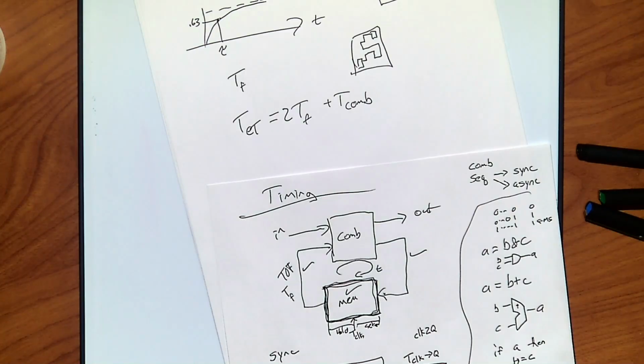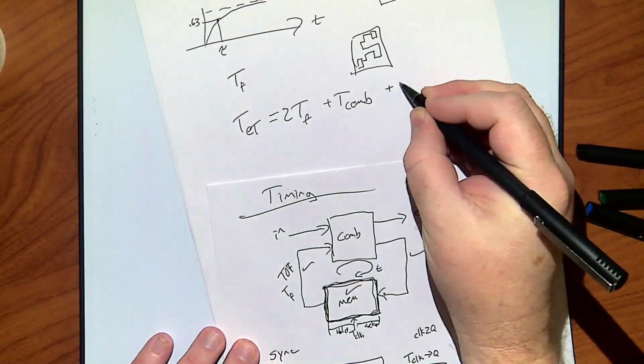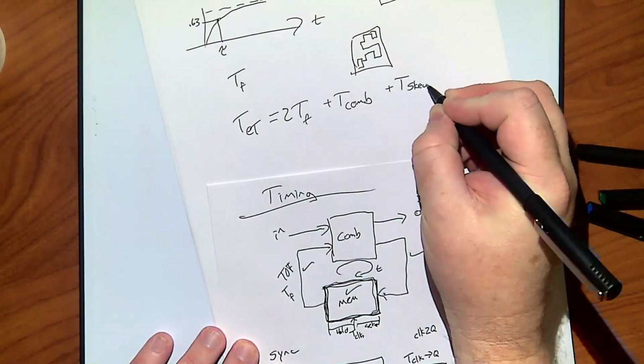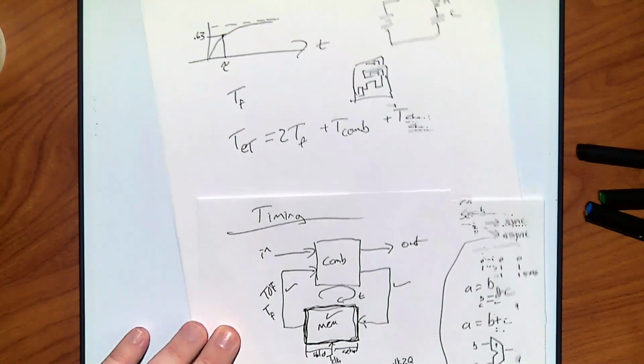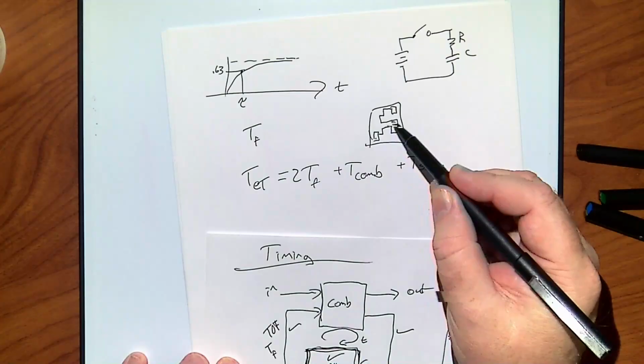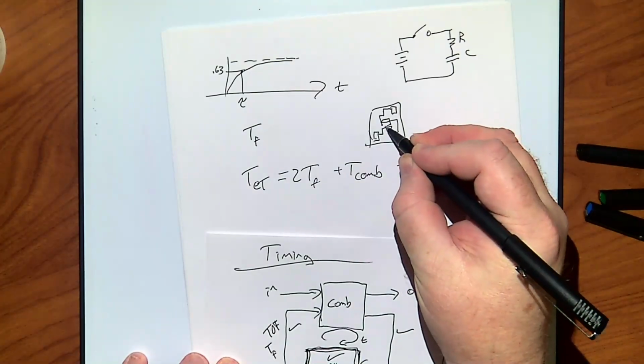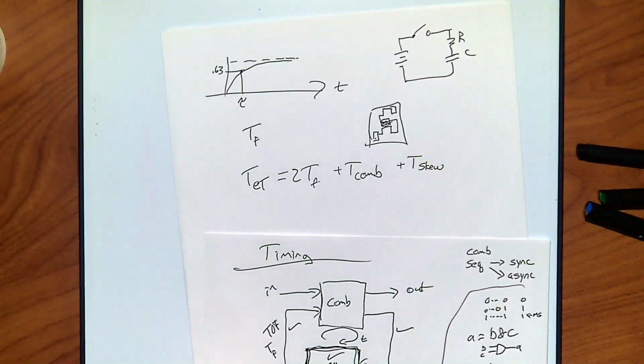Does all this make sense? So when I'm doing the comparisons, I have to take the time of flight and the combinational logic. Oh, there's one other thing, let me just mention real quick. It's called T-skew. Right now, everything we've done is telling you how to go from this particular launch here. I'm starting at a register and coming back to that register. In reality, when you're dealing with a system, you might start in this one and end here, and maybe the combinational logic was here, right? You're not starting and stopping at the same one.